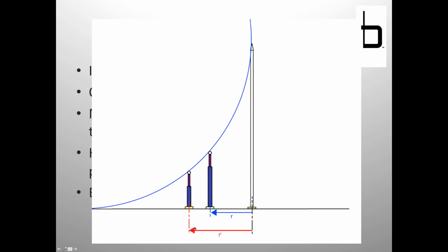It's kind of the brim of the witch's hat. There you go. That's exactly right. So we're getting closer to the brim away from the center. If our equipment is shorter, we'll have more radius of protection, meaning we can put our equipment further away. So this is something that we can calculate, right? We have the formulas, we have the geometry. We can calculate what this R is based on a given equipment height.